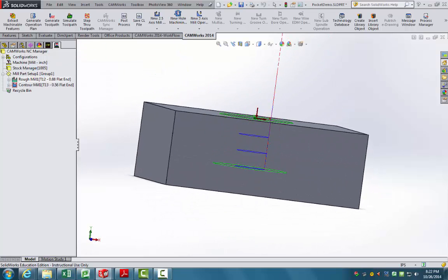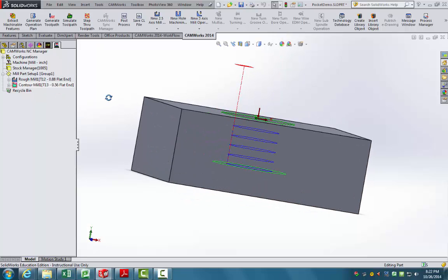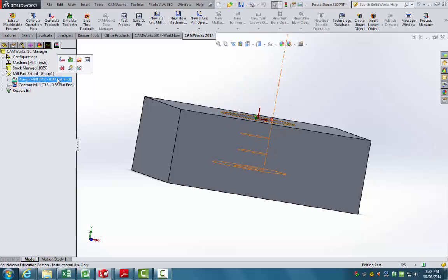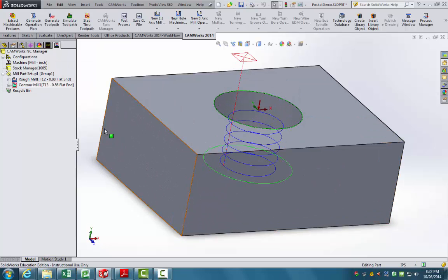And this looks good. We can see that a step relative to our end mill size is reasonable. Our smaller end mill is stepping down more often because it can't step down as far, because it's smaller. The general rule of thumb is something along the lines of half of your diameter. So this is coming down maybe 0.4 inches at a time, whereas the smaller end mill may be only coming down 1/4 of an inch at a time. And this seems reasonable.